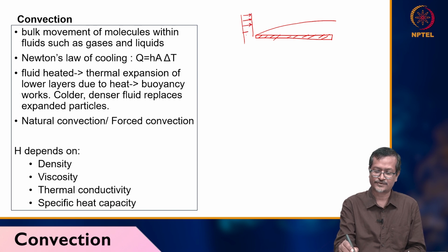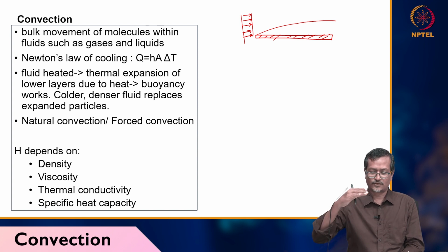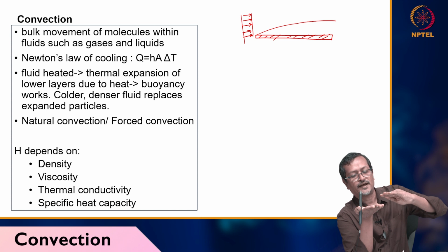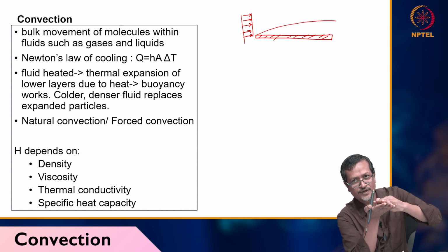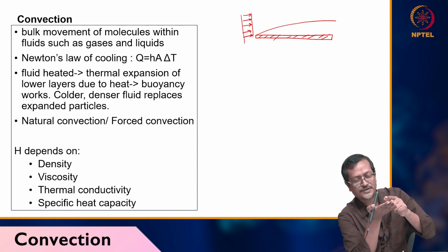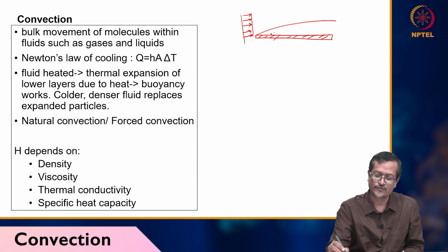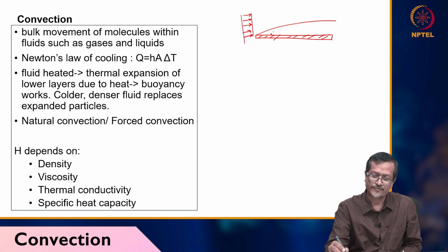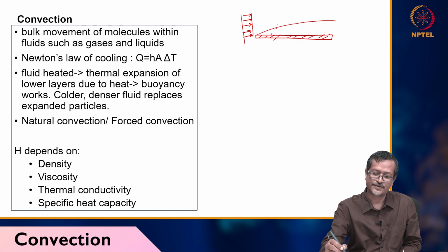Equal flow velocity you are giving, but whenever it is going over the flat plate, near the wall, let's say this is my wall and fluid is flowing over it, the fluid particle will not be able to move with the upper layer. Because of the no slip condition, near the surface the fluid will have very low velocity because of friction. But if you go a little bit up, a higher fluid velocity will be there, then further higher fluid velocity.